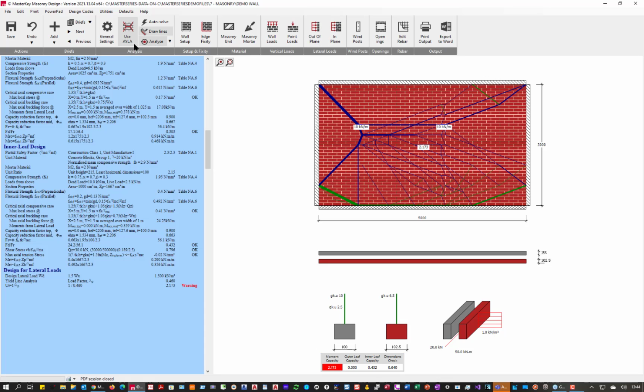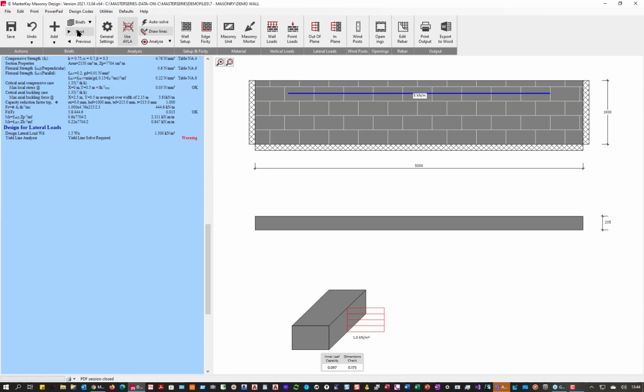So the last thing I want to look at is coming back to these, but this is like a freestanding wall, say in a car park, that's fixed into the columns at either side and the base, and it's got a 5 kilonewton per meter surge load onto it, plus a bit of wind, and they're always assumed to be going in the same direction, by the way. And we will see that we need to just do our solution.